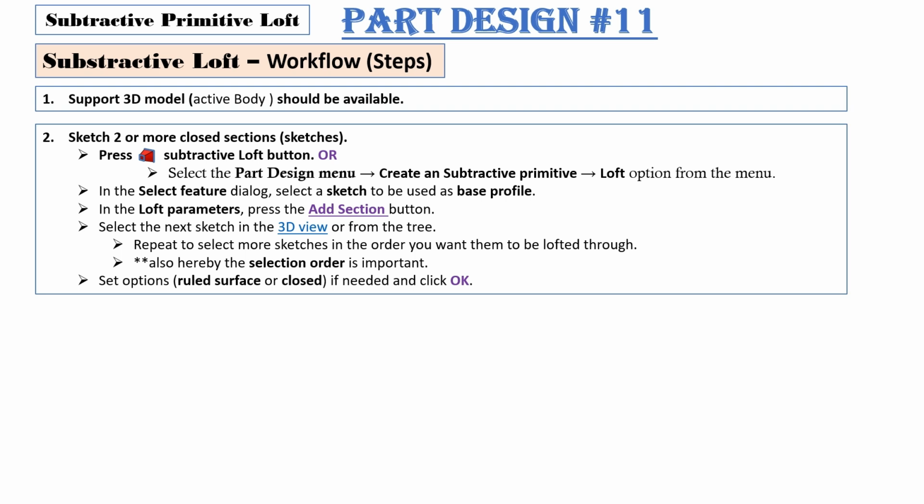The next step is selecting a sketch to be used as base profile in the dialog window. Then, press OK. Now you can add the other sketches in the order you want. You can also set options like ruled surface or closed if needed.